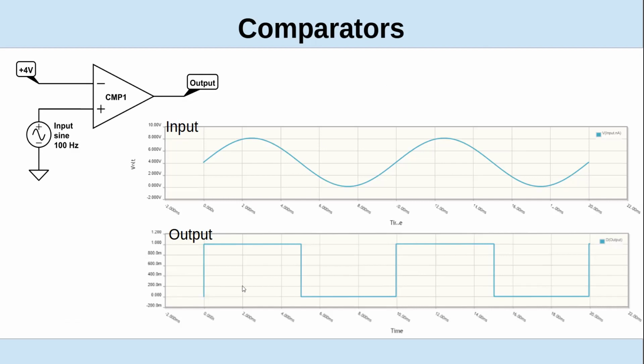In this case, it's set up so whenever this input signal exceeds 4 volts, which is what it's starting out on this waveform, it's going to go true. And it's going to go false again when it gets to a lower value, and there's some hysteresis in it, which is why it goes off at a lower value than what it triggers at.